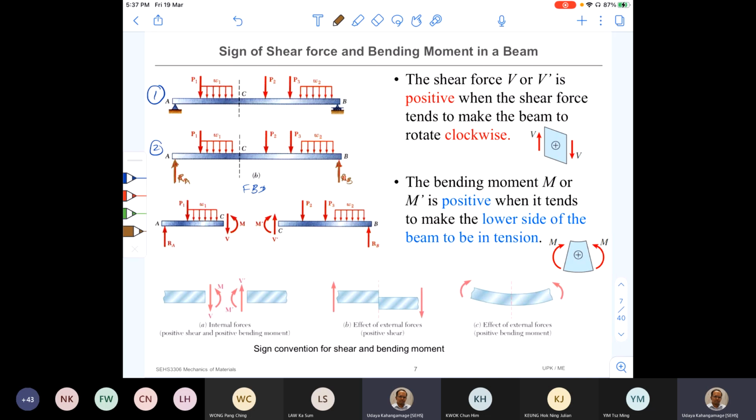Okay, and then to construct the shear force diagram and bending moment diagram, we need to find the internal shear force and internal bending moment. So that means we need to cut this beam at different locations and find the shear force function and the bending moment function, because they vary. So we can define them as functions. Right?